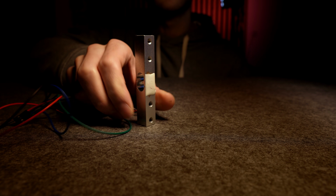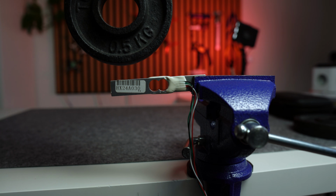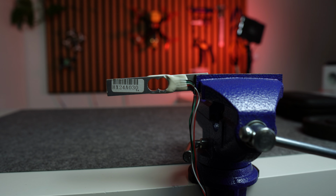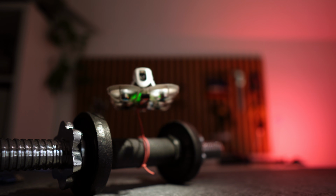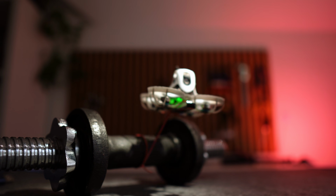Version 1 used this load cell, and honestly, the only reason was that I already had it lying around. It's a load cell that can measure up to 5 kilograms, which sounds fine, right? Well, not really, because Whoop motors don't produce thrust anywhere near a kilogram. At first glance, that doesn't seem like a big deal, but let me explain for a second.